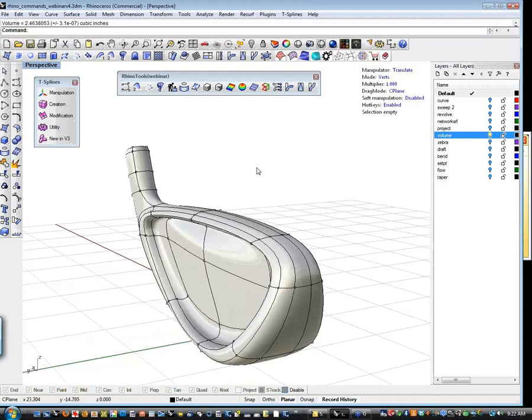Yeah, I just want to chip in. I think some of these analysis tools are some of the most powerful things about how you can integrate Rhino with T-splines. So using things like this volume calculation, then just tweaking the control point to change that, I think is really powerful. And as far as getting that to update in real time, that is something we're looking at getting in. But if you are a Grasshopper user, it's very straightforward to hook up a little Grasshopper setup so that you can see that updating with Grasshopper in the meantime.